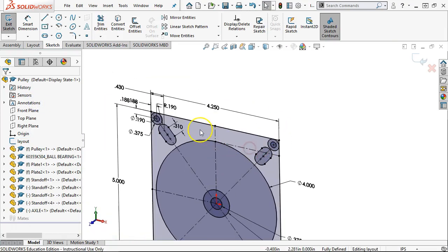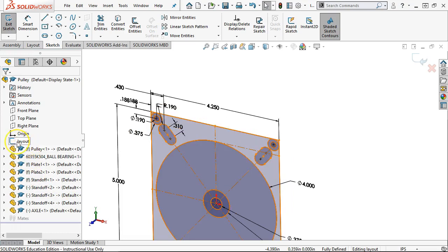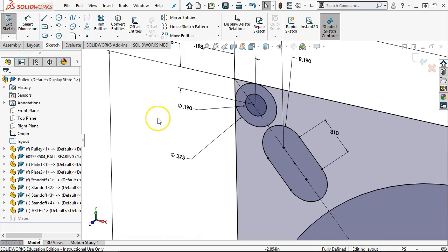So what I want to refer to is that as you're going through this process, if I tied plate 1 to plate 2, which was tied to the pulley, which was tied to something else, we'd have a lot longer line of traceability back through these parts. Having the single layout sketch is me trying to reinforce that single point of failure.